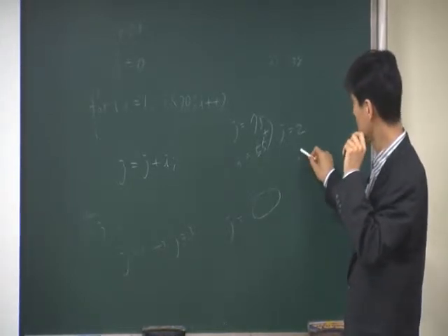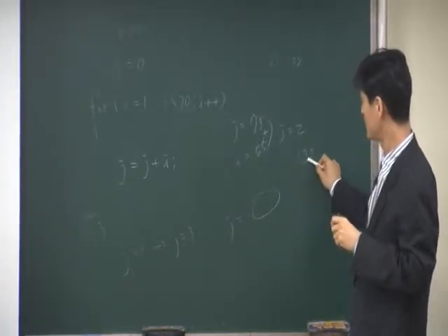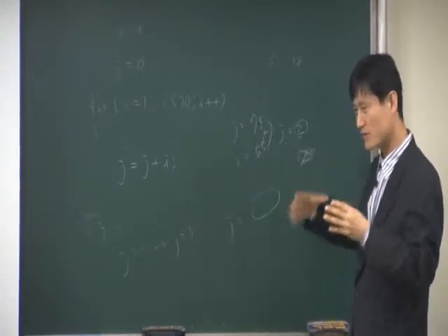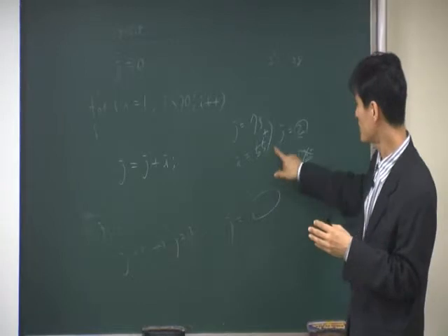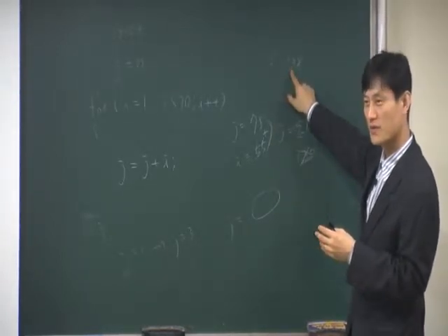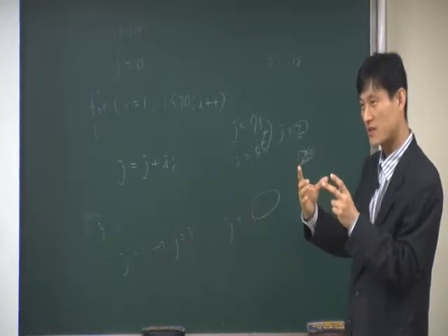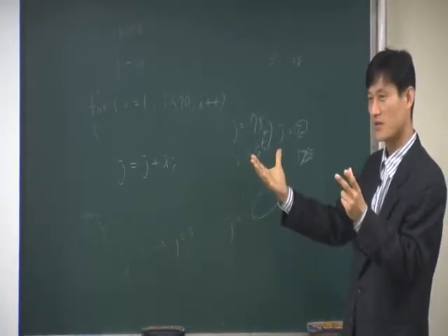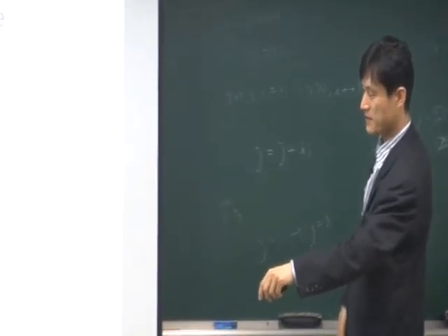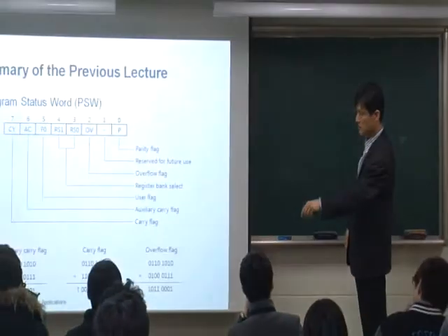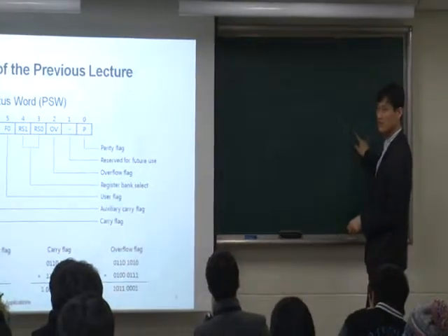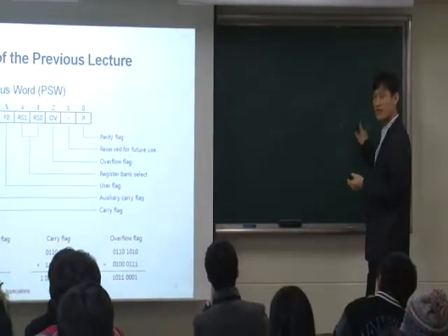You basically guess that it should have 130, but instead you're going to have 2, right? Suddenly the value is reduced because the output is bigger than what you can hold. Your container is only this much, but the value is much bigger. So this overflow, this kind of carry happens. So carry flag is on, but the actual output remaining in the container is just 2. So definitely it's an error case.